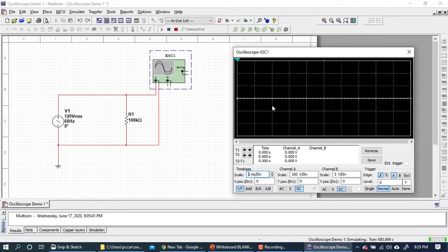The old oscilloscopes, they have a time-based control. They have a volts per division control for the channel. And they also have a graticule on the screen. That's what the grid is called. And so you can take the graticule that's on the screen, the settings on your time base, and the settings on your channel on a 50-year-old oscilloscope, and you can come up with what we just came up with. 16.66667 milliseconds for the period.